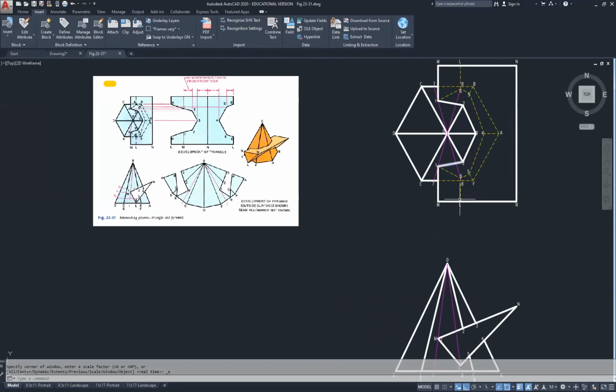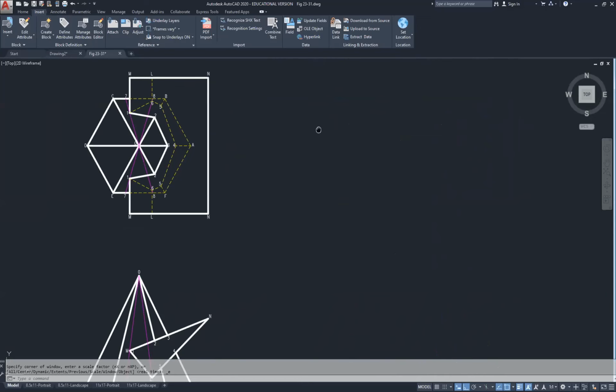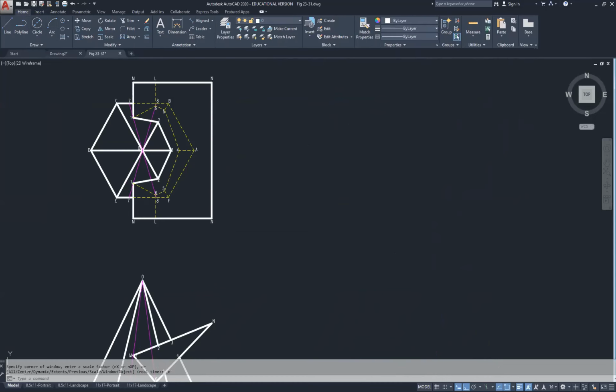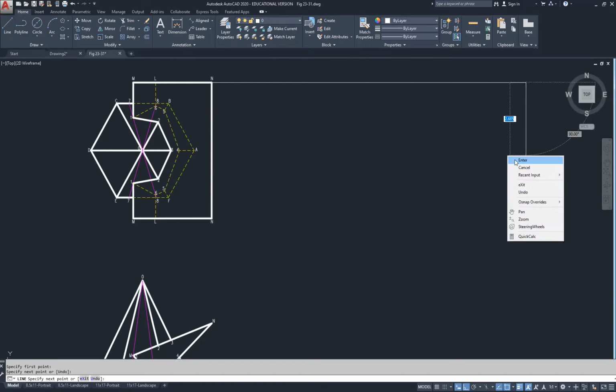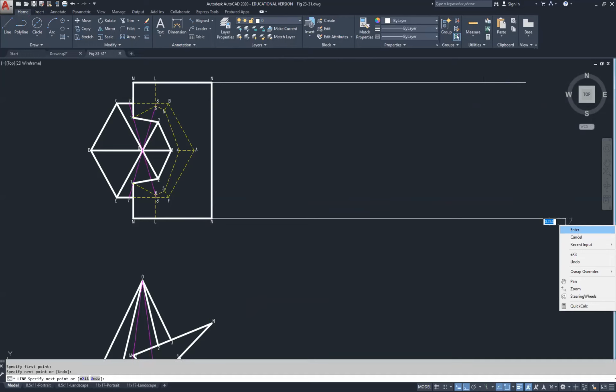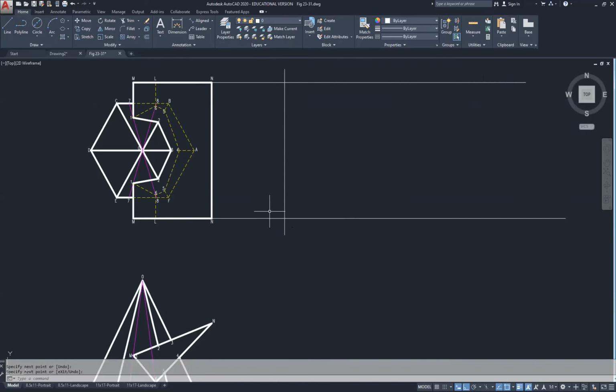Now what we're going to do is take the information here and turn it into a flat surface development. We'll start with the surface development of the triangle, and we'll move on into the pyramid. So now we can begin. We'll start by projecting line work from the pyramid, or from the triangle over. Doesn't really matter how far over it goes right now. Just going to project some line work. Then I'm going to have a line that crosses across here. This line here is going to be the edge of the triangle.